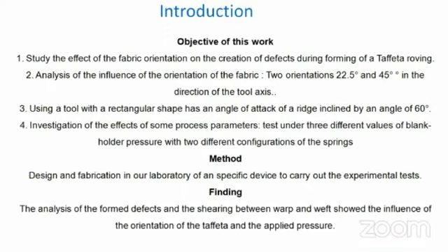Method: design and fabrication in our laboratory of a specific device to carry out the experimental tests. Finding: the analysis of formed defects and the shearing between warp and weft showed the influence of the orientation of the taffeta and the applied pressure.